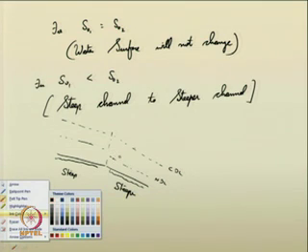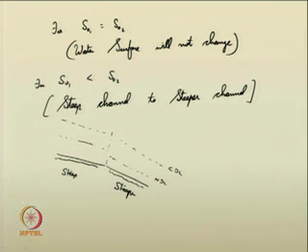So, all these things suggest that you can have only one theoretically possible water surface, and that is the flow exists in normal condition up to this junction in channel 1, and from there it goes like this. So, this is having an S2 profile.